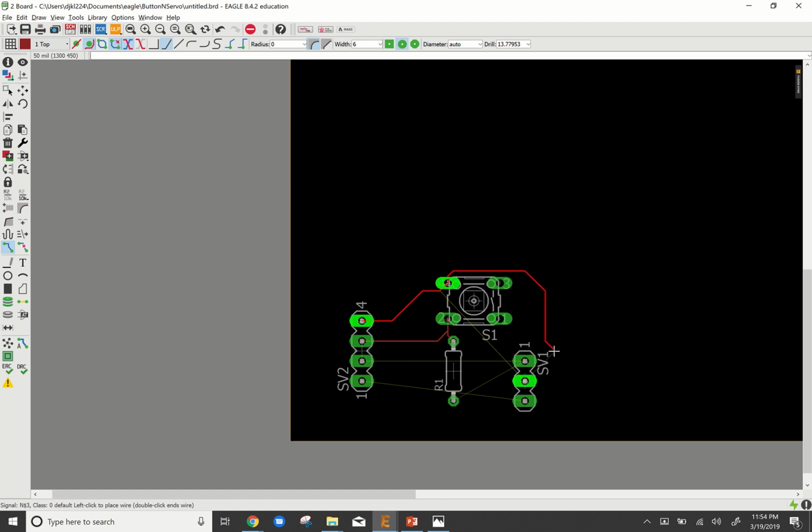And so I'm going to go around the back here and in on my power wire for my servo. I'm then going to have my wire come in for my signal to that same servo. Let's go down here, go over, and then go back up. And that leaves just the connections for my ground. Right there. Right there.